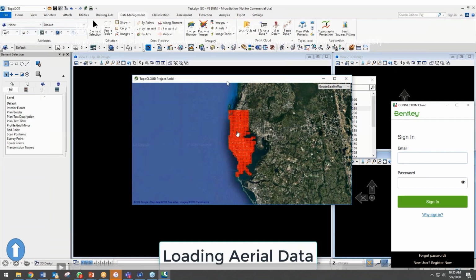And then a couple hours to take all this data. It's 302 square miles. We basically took all that data. This was airborne data, 50 or 30 points per square meter, Geiger mode, if you're familiar with it. And basically we chopped it all up.